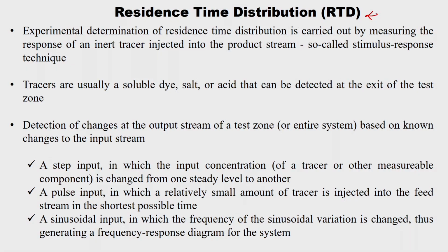So, it is very important to know that each and every particle spends the required time at the required temperature. Because of this, for pumpable fluids the RTD calculations are very important to find out whether there is a change in the residence time distribution of the particles or not.